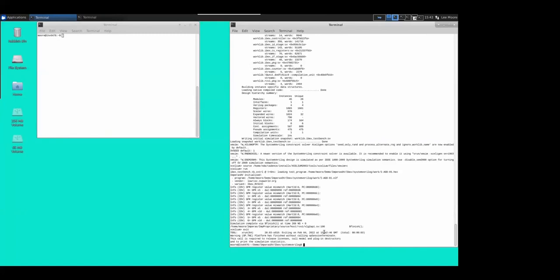And what it tells us here is that at this program counter where we've executed an instruction, which is D8, we've got a miscompare. It's telling us that the device under test told us that the value of the X5 register was 0, and the value of the X5 register in our reference model under Imperas DV was D8. Because we've got the miscompare throttle set to 5, the program does actually continue executing, but of course this is continually reported. And then we see a further miscompare at this point, where we also have a miscompare in X10.